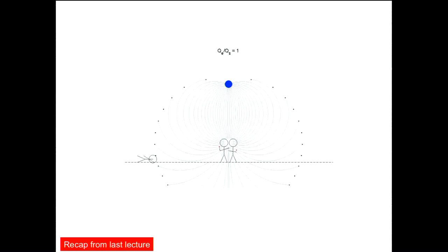Now, there was one very glaring problem with our first attempt of the smoker's problem, and that is our bottom boundaries, right? So you can see that there's flow coming in and out from our floor, but that's not physically possible, okay? So we want to make sure that our bottom boundary here is impermeable, right? So basically, my velocity v is 0 along this line here. And to do that,